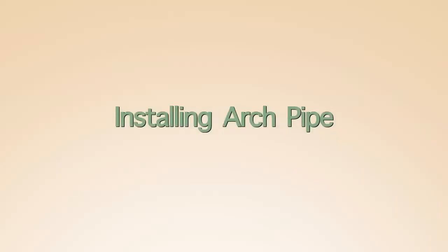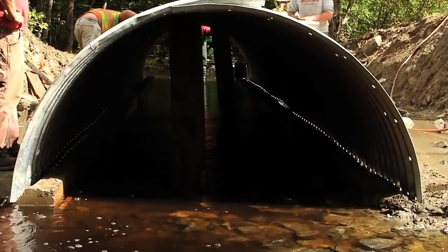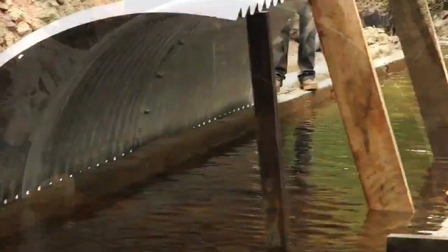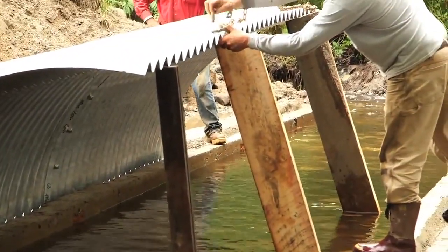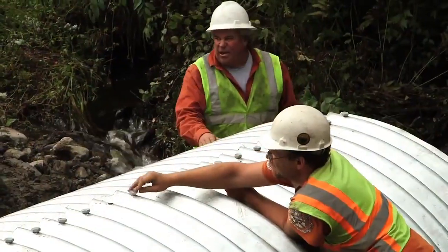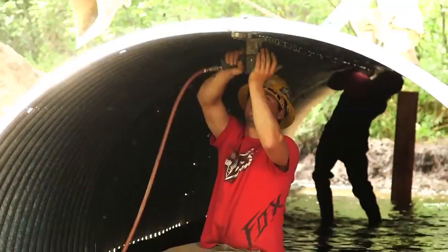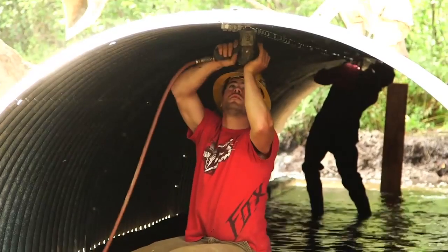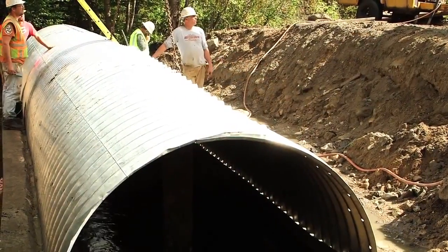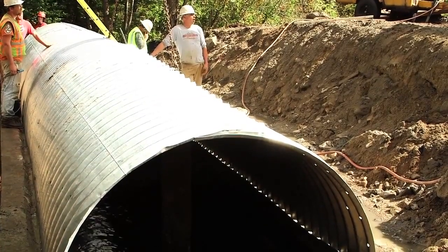Installing the arch pipe. The arch pipe was a 4-foot, 2-inch high by 8-foot wide single-span arch. The full span of the arch was formed by bolting together smaller plate sections. Several plates were bolted together out of the stream site prior to placement to minimize the amount of time spent in the streams assembling the pipe. This allowed the pipe to be placed on the footings with just 4 pre-assembled sections.